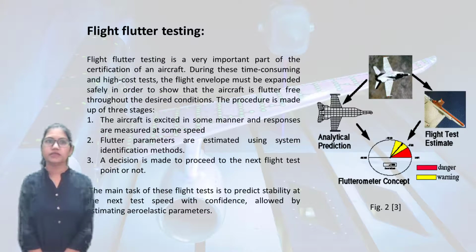The next topic is flight flutter testing. Flight flutter testing is a three-step procedure. The first step is the analytical prediction, the second step is the flight test estimation, and the third step is the one in which the decision is made whether to proceed to the next flight test point or not.